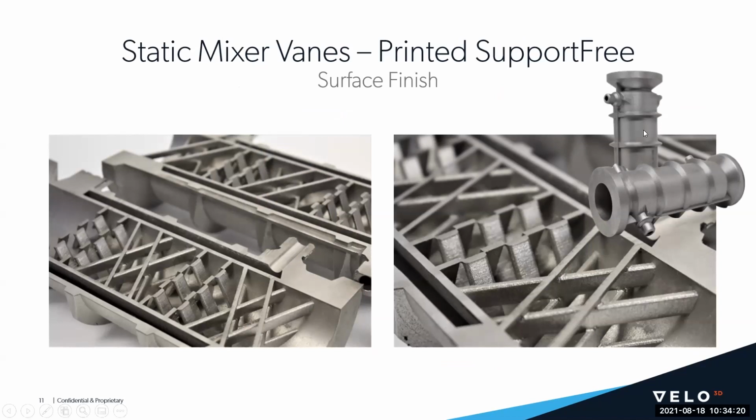Traditionally, a hole this size, it's about 10 millimeters, would need to be modified to be printable, or it would need to be supported on the inside. Otherwise, it'll become extremely rough, or maybe just non-circular, or in the worst case, it could just crash your print job. On the other hand, our software adapts to geometries like this by applying our low angle process to produce a circular hole, and with a surface finish that we can be satisfied with as printed.